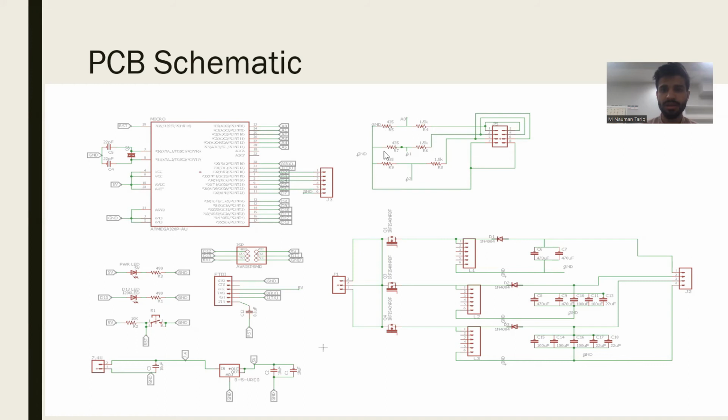So firstly, coming towards this is the VDR circuitry, and these are the input part of our project. The first three pins are our input pins and the fourth one is ground. We have connected a 4x2 pin here because firstly our input comes towards the input part of our project, and then it will move towards the VDR part. The voltage across the second resistor will be sensed by the A0, A1 and A2 analog pins. It depends upon which input is coming: input 1, input 2 or input 3.